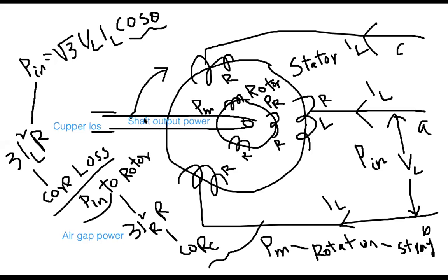So to calculate the efficiency, if you are asked to find it, efficiency is power out over power in. Your output power will be the final shaft output power, and the input is the actual input power, which was available here. Then you just multiply by the percentage, so you will get the percentage efficiency. Okay, so let's go back and solve a problem, then you will be fine.